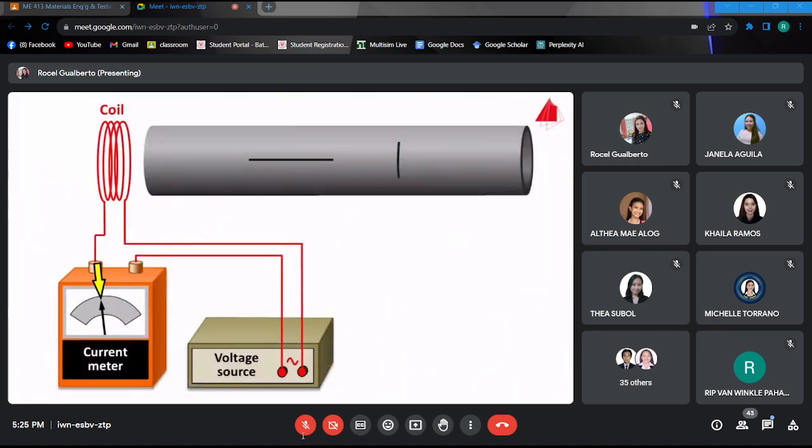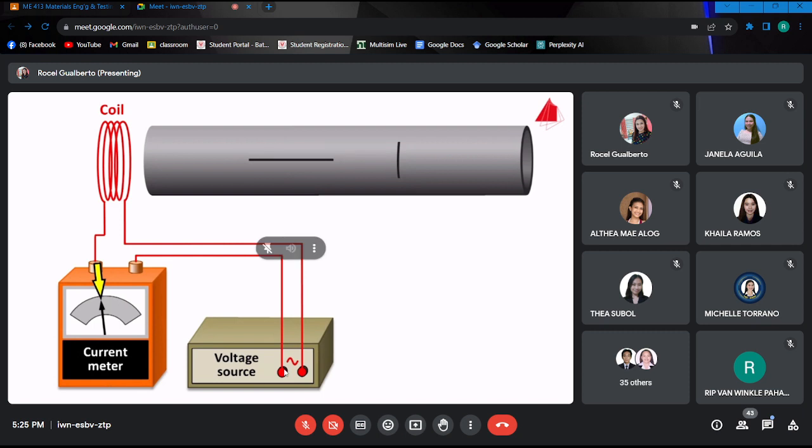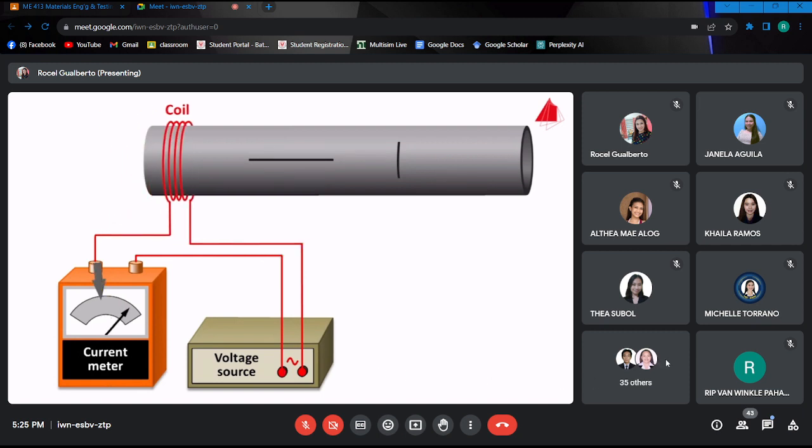Low current consumption as long as the coil is still far away from the tube. The reason for this is the undisturbed self-induction. Much higher current in a region where the tube is intact. The reason here is the eddy current, its own magnetic field, and the reduced inductance of the coil.